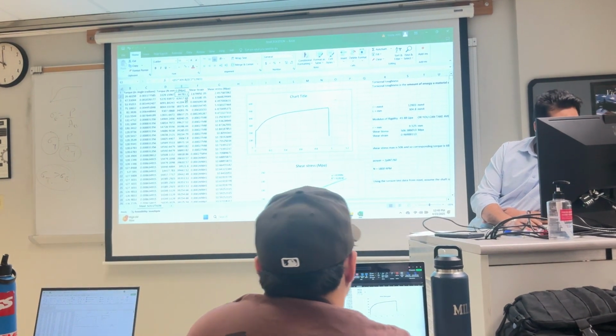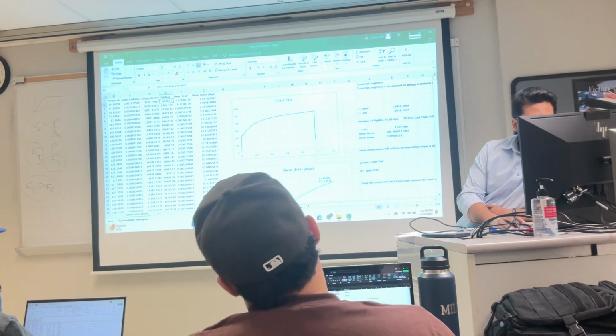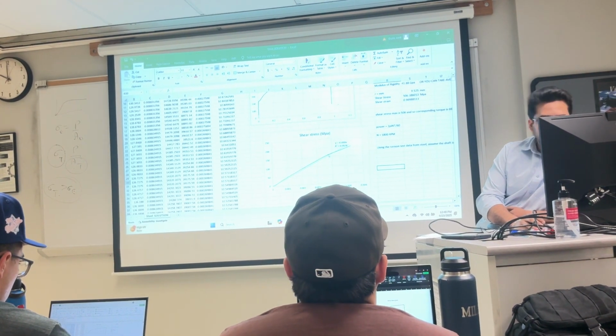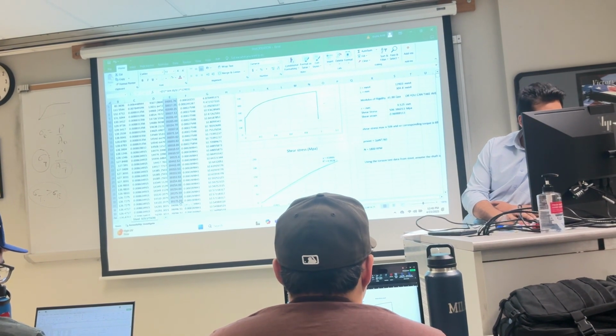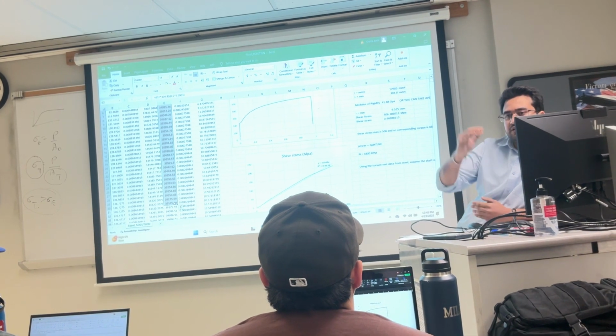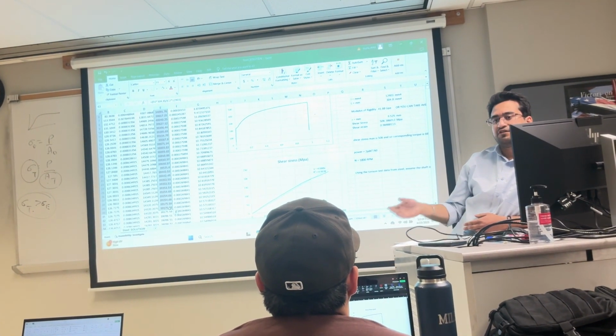That's what I'm saying. Generally we take the average though, but that doesn't give a right answer. Because of the elastic limit you have to pick, or you can do the averaging of the first 40 data, 30 data. Because you have to see only the elastic region, you know? You can't take the entire range for the maximum.